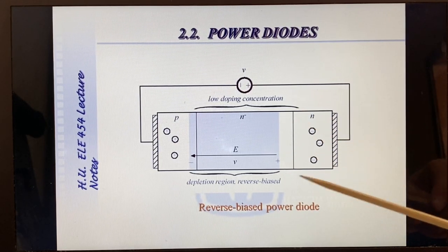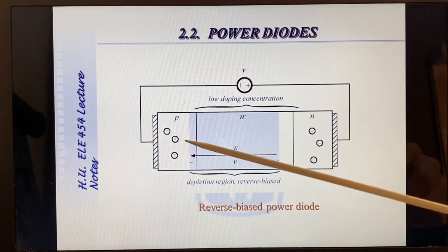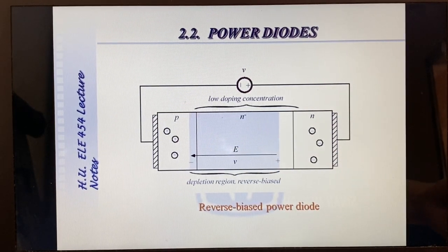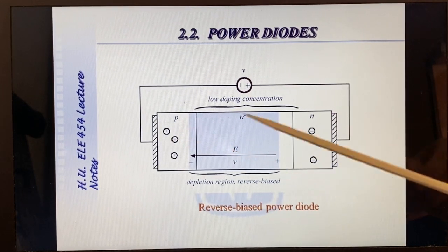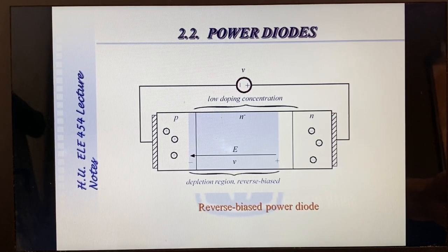In the P-type material, there is a lack of an electron, that is, a free hole at the outer orbit, as in the case of boron. The silicon materials doped with P and N-type impurities are brought together in a junction, so they make a PN junction.